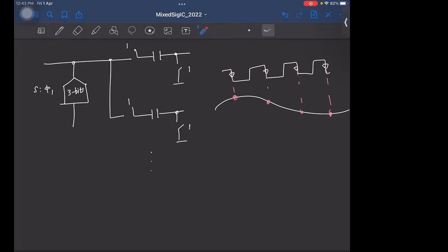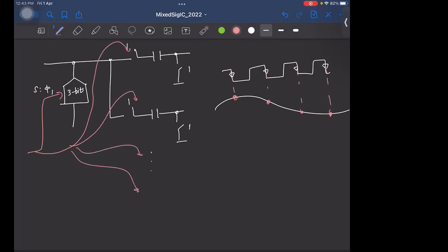that has to be distributed throughout your design, right? So let's say phi 1 you generate somewhere here. So this goes to the ADC here, and then this has to go to each of these branches, right? Now, can you comment on the relation between the clocks that the ADC receives here and the clock that is received by the switch here? Will they be identical, or will there be any mismatch between them?